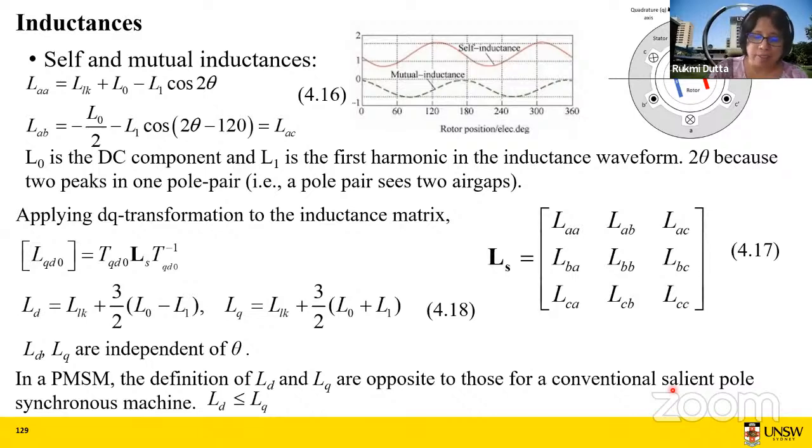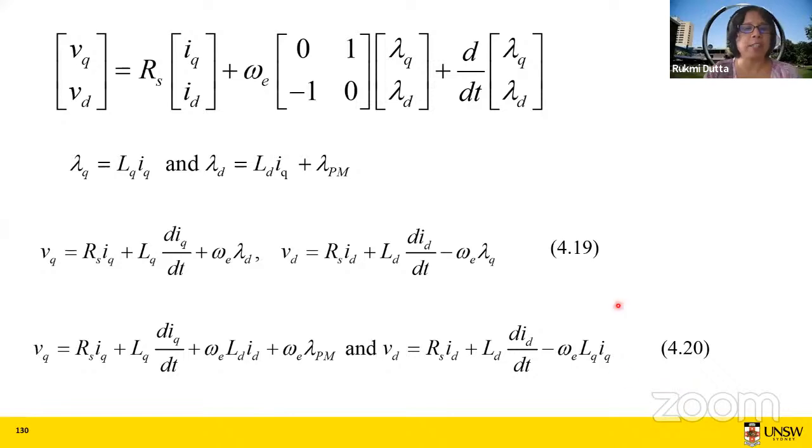It has also converted the voltages VD, VQ, the currents ID, IQ, even the flux linkages lambda D, lambda Q. All these quantities have become time independent. If you do some maths using sinusoidal current and sinusoidal voltage and do that matrix transformation, you will be able to see that the omega t term disappears and they become DC quantities.